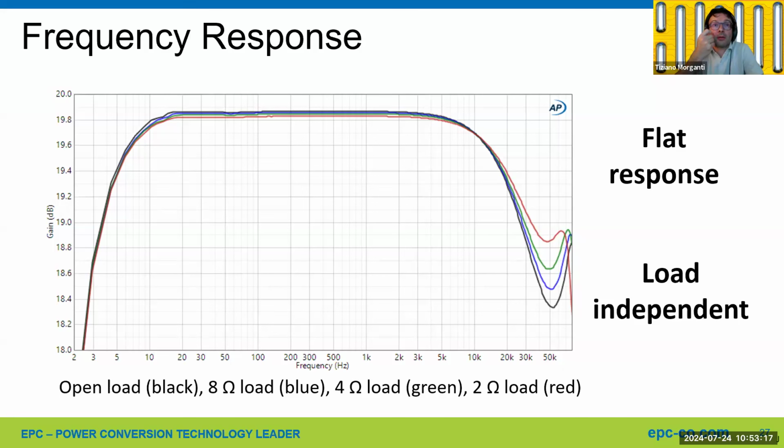Well, we have that one going on with this kind of feedback, actually, but it's not direct current measurement, it's indirect current measurement. So we estimate the current ripple in the inductor by derivative of the output voltage. So you have the ripple voltage in the output capacitor. If you do a derivative with a capacitor, so a high pass filter with very high corner frequency, you get an estimate of the ripple current in the capacitor, which is in turn the ripple current in the inductor.